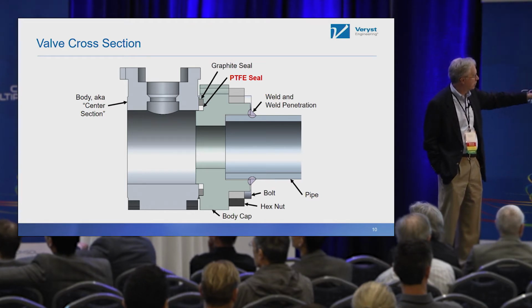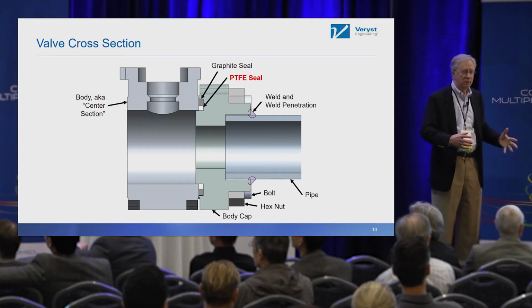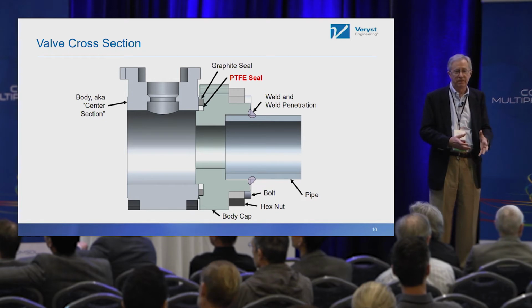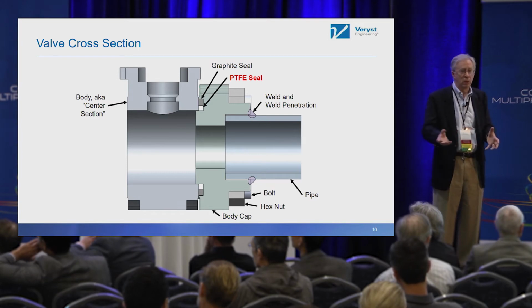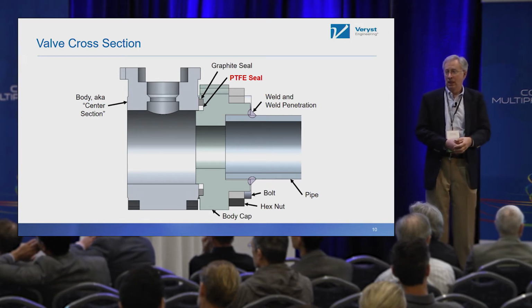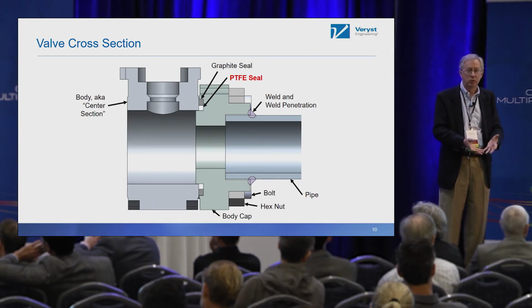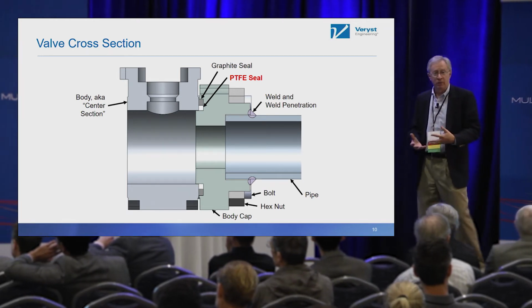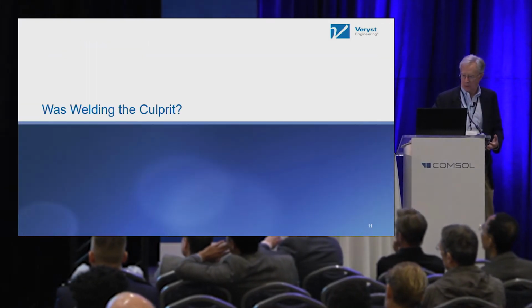The seals are compressed by bolts, so when the valve is assembled, there is both a graphite and a PTFE, a Teflon-like polymer, which is compressed to provide the seal. That is delivered and then welded as is. And the reason why you control the temperature is pretty obvious. We have polymer components inside, and we want to prevent those polymer components from getting too hot.